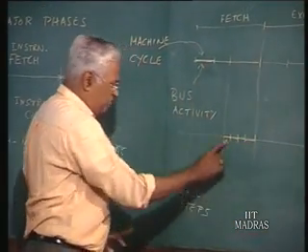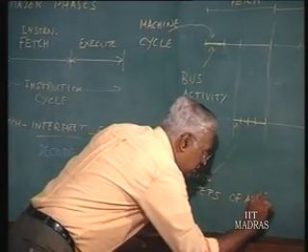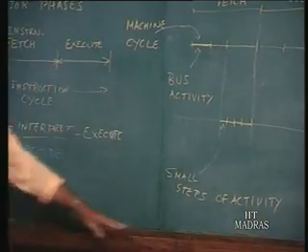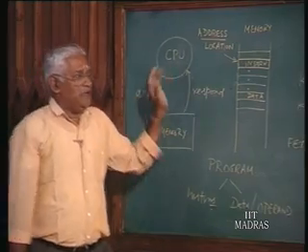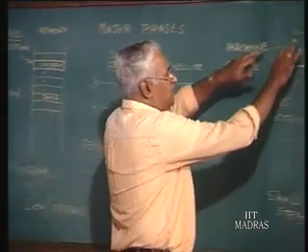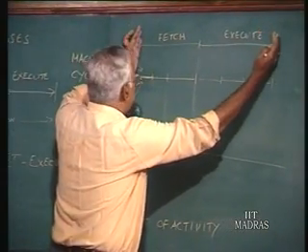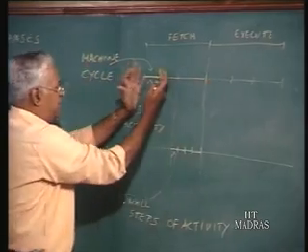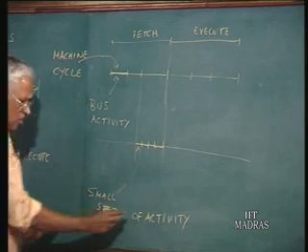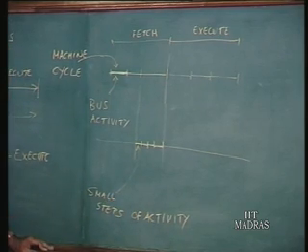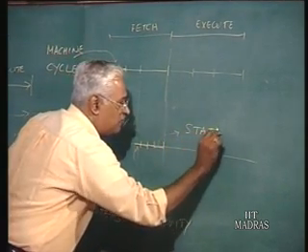What is that? To understand that, we really have to go into the details of the processor, which is what we will shortly be doing. Now, we can summarize that essentially the program is executed by taking instruction after instruction. The instruction cycle consists of machine cycles, and in each machine cycle there is some bus activity, and each machine cycle consists of some small steps of activity, right. Now, specifically each one is called a state of the processor.